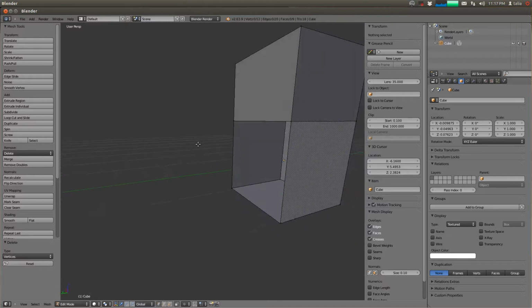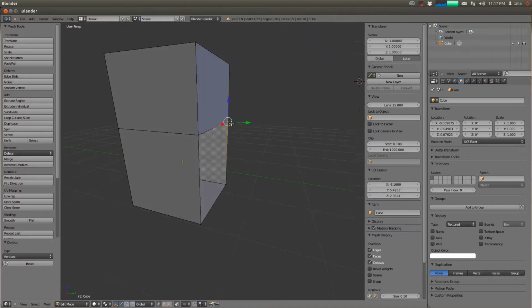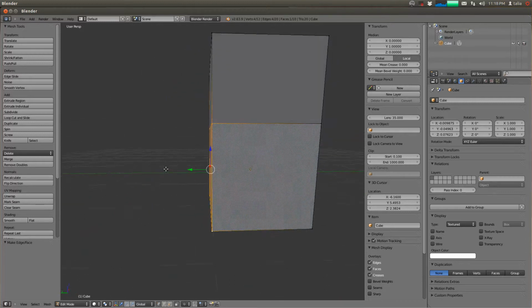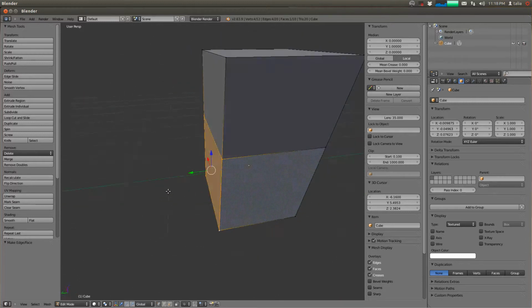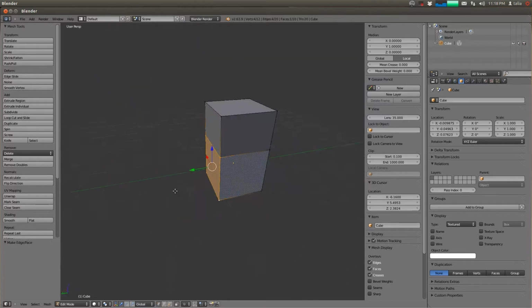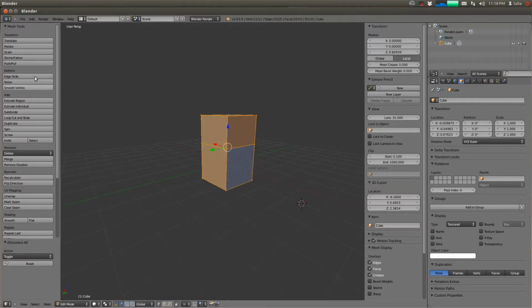So now I'm left with a hole in the mesh here, so I'm going to patch that up really quick. I'm going to right click and select the individual vertices again. I'm going to hit F, and F will fill in the face attached to those vertices. Now, I'm still left with my double height box here, and let's talk a little bit about normals.